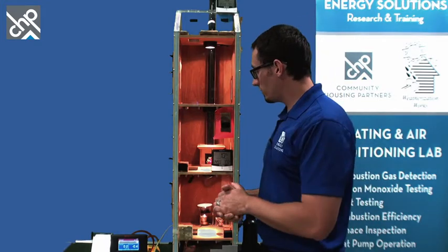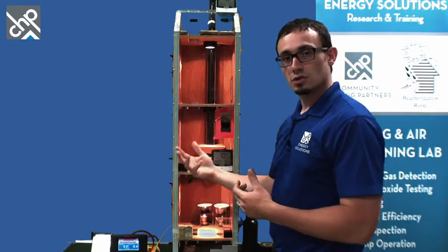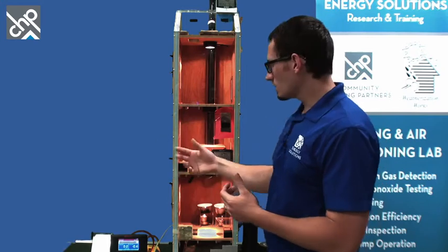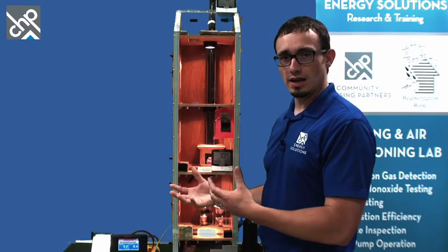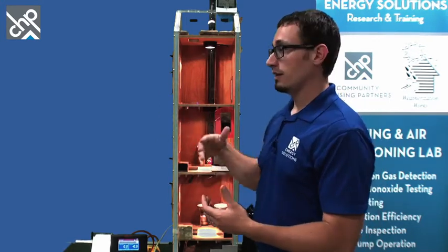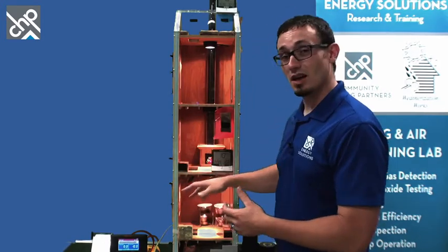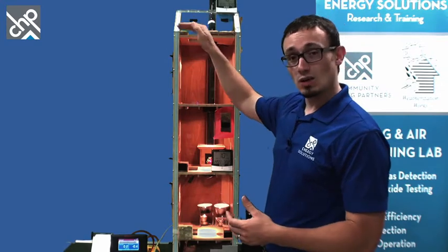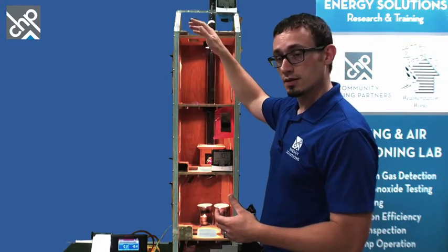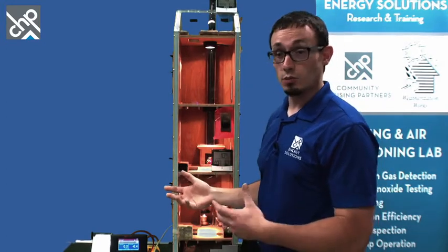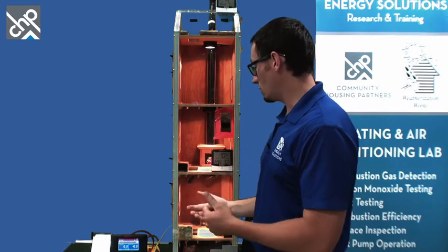And we know that if we've got a temperature difference between inside and out, that heated air is going to have the tendency to move in the building. So that heated air wants to rise up and out of any holes that are in the top of the building. And then as we have CFM that escape, what has to happen? We have to have CFM coming back in. You have to have that air coming back in from somewhere. And usually that's going to happen lower in the building.